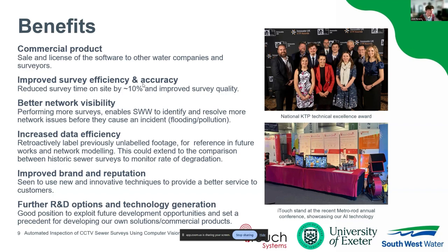If we are able to label that up, we can then start comparing between footage, so looking at degradation of faults over time. So actually find out that, say, a structural defect that we recorded, I don't know, 5 years ago in a pipe hasn't actually decayed over those last 5 years when we've done the next survey. Maybe we can triage our systems and spend that money elsewhere for the time being, because it's not causing any problems in the meantime. So that would be a really great benefit to our asset management team and those guys that are planning out our kind of big strategic works.